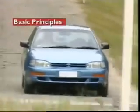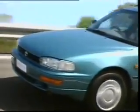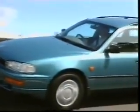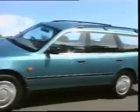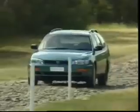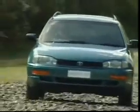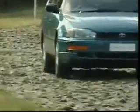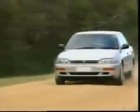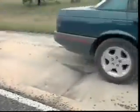This section examines basic principles of light vehicle suspension systems. The suspension system isolates the body from road shocks and vibrations, which would otherwise be transferred to the passengers and load. It also must keep the tyres in contact with the road. When a tyre hits an obstruction, there is a reaction force. The size of this reaction force depends on the unsprung mass at each wheel assembly.